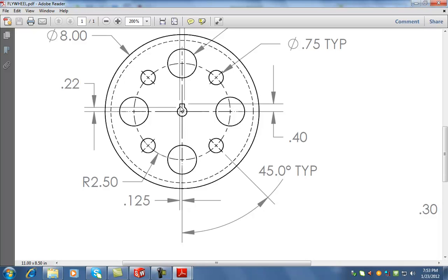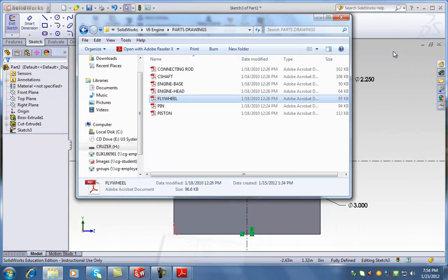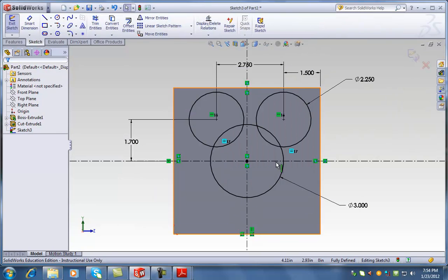So how can we create this? Well, the first thing we have to think about is, this shape is not even part of SolidWorks, right? SolidWorks has circles, it has rectangles, but it doesn't have both of them together. So one of the things I have to think about is, how can I combine multiple shapes to create this complex shape? That's exactly what I'm doing here. I have multiple circles in order to create a more complex shape. Now, the problem is, is this a good sketch?